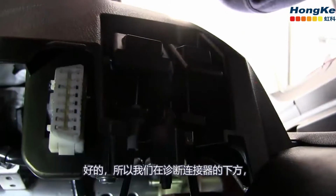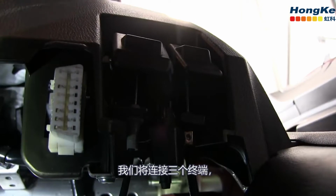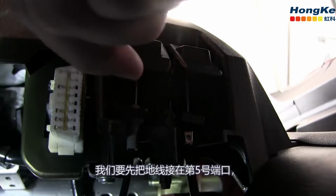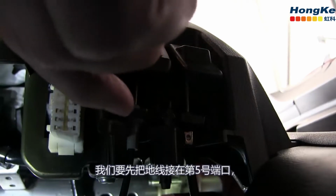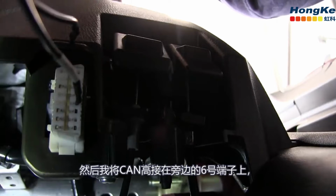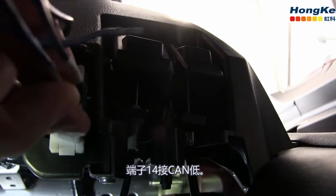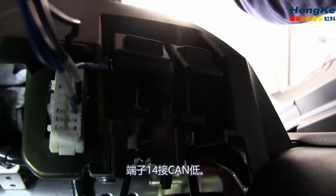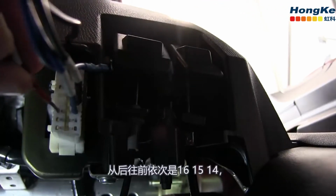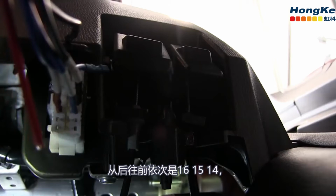Okay, so we're down here at the diagnostic link connector, which is the white connector on the edge of your screen. I'm going to connect our three terminals. We want our earth first, which we'll put on terminal 5. So there's number 5 on the top. Then I'll put CAN high on terminal number 6 next to it. And then directly opposite that, we've got our CAN low on terminal 14. An easy way to get to that is we've got 16, 15, 14 from the top at the back.